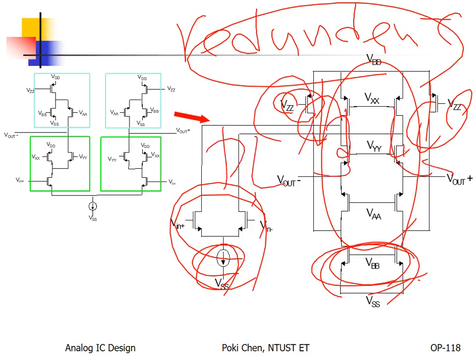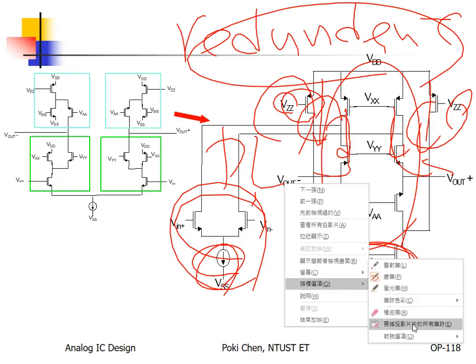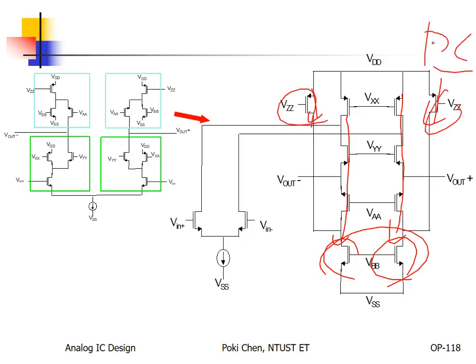All those DC currents don't have any impact on such AC operation. So you can see, you have DC current here, DC current here, and also bias current here, and they are summed up to the bottom transistors. It doesn't make any sense, because those two DC currents only waste your power. They don't provide any gain.